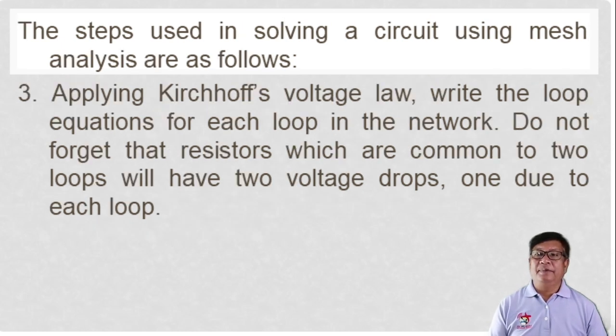correctly. Okay. Number three, applying Kirchhoff's voltage law, write the loop equations for each loop in the network. Do not forget that resistors are common to loops with two voltage drops, one due to each loop. Okay. That is number three.